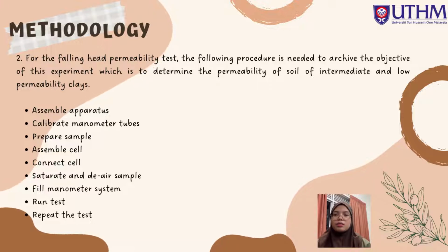The manometer tube's cross-sectional area should be calculated for each tube as follows. First, add water to the tube until it reaches a known mark that is located close to the top of the scale, until the level in the tube has dropped by at least 500 mm. Run off water from the tube into a weighed beaker. To the closest millimeter, read the new water level on the scale. Weigh the water-filled beaker that came out of the tube. It is possible to determine the manometer diameter for each tube. Repeat the measurement 2 or 3 times, then average the findings.